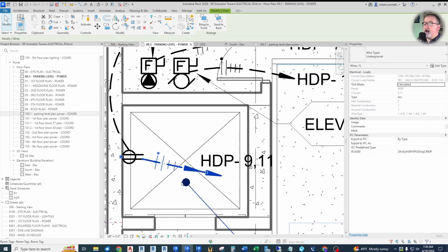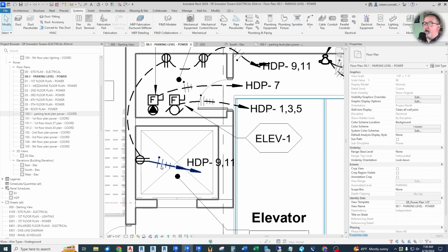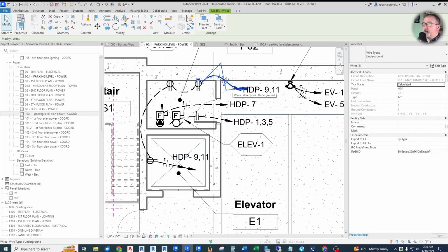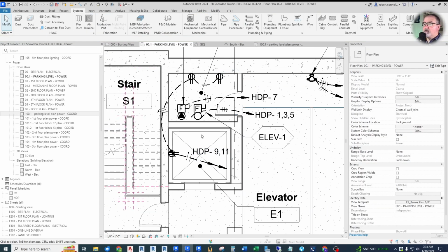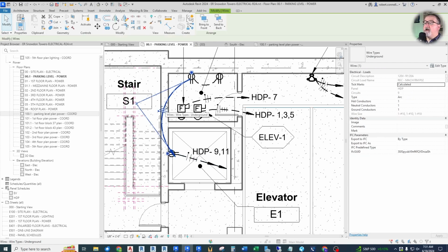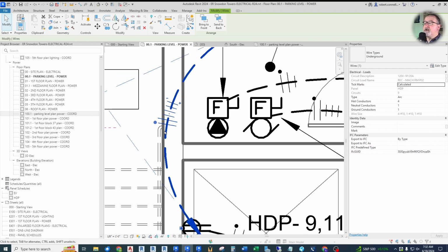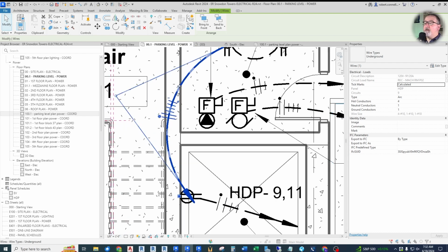Let's move this out of the way. It added the additional hot wire in here for me to show 2 circuits. And then I can actually just delete this home run. So speaking of the hot wires, except for this multi-circuit home run, if I click here, I can actually add additional hot wires to this conduit if I need to. And it's just mostly used for lighting, when you may have an always hot and a switched leg or a switched hot, you may want to add multiple hot wires, phase conductors to this run.